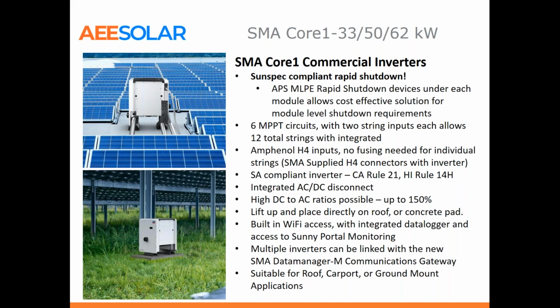One note here, the inputs: since this inverter is used both in Europe and in America, and Amphenol H4 is more common in Europe, they do have Amphenol H4 connectors. So on the inputs, they do give you the connectors. They give you 12 connectors, 24 connectors, sorry, 12 male and 12 female to plug into the inverter inside the inverter shipment.